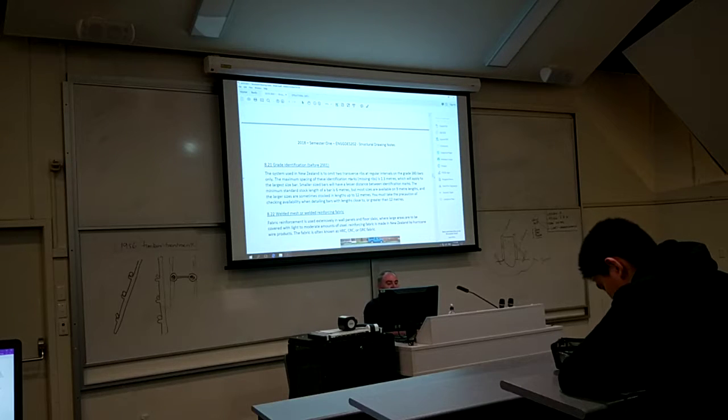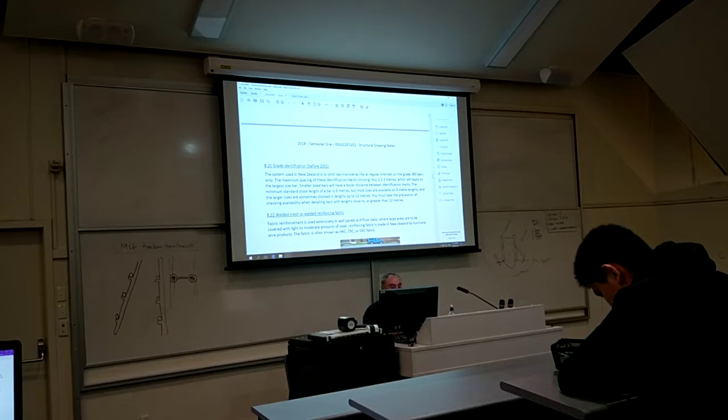If you could design it to their 9 metres by 12 or something, or even with an overlap, so that you're using, say, 2 9-metre bars. So there's a little bit of working out involved there, which I have in the past made students do. The good thing for you, you don't have to worry about that in my assignment.